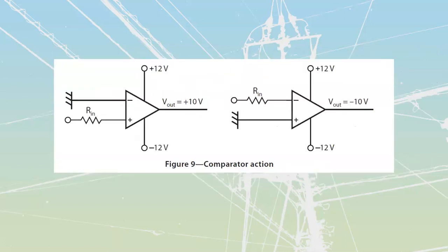Okay. Next thing that we're going to talk about is going to be the comparator. The comparator is going to be similar to the differential, only instead of us having two values of voltage, we're going to fix one value of voltage. It could be fixed at a value that is going to be ground, like this, or I could fix it at any other reference value of voltage.